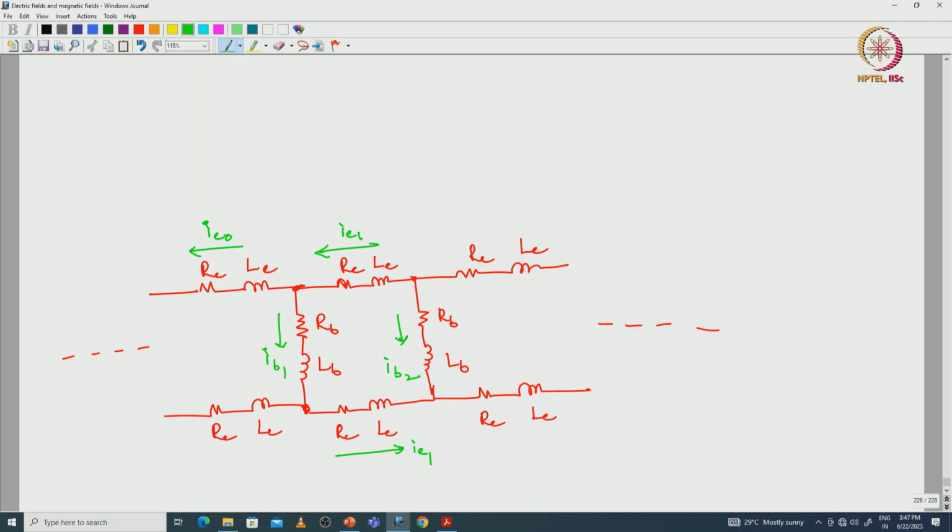In order to find the equivalent resistance for the rotor mesh, first we have to know the resistance of each skewed bar and the resistance of each end ring. So, we will calculate the resistance of the end ring first.